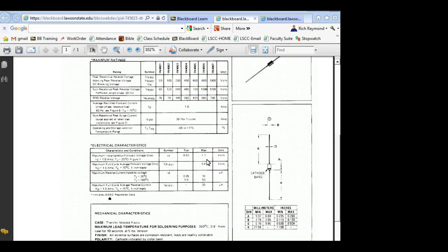Yeah, so if you calculate the output's supposed to be 15 volts and you go in there and measure 5, then you know something's wrong. But if you don't know how to calculate it, if you don't know what it's supposed to be, and you measure 5 volts on the output of a DC power supply, you might say, well, that's good, I measure something, right? You understand? You measure 30 volts and it's supposed to be 15.